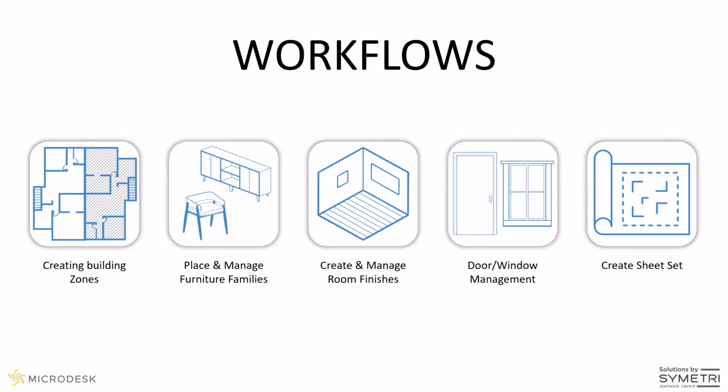Then we're going to look at managing our room finishes, actually creating those 3D floor finishes, wall finishes, and ceiling finishes based off of our rooms, and then creating room drawings from that. Looking at door and window management, being able to number our doors and windows with a variety of parameters specifically based off of our room numbers, and being able to create those door or window drawings to put into our documentation set. And lastly, putting together entire sheet sets for our plans, easily creating those plans, creating those sheets, and then batch modifying data of our sheet sets. That's what we're going to look at today.